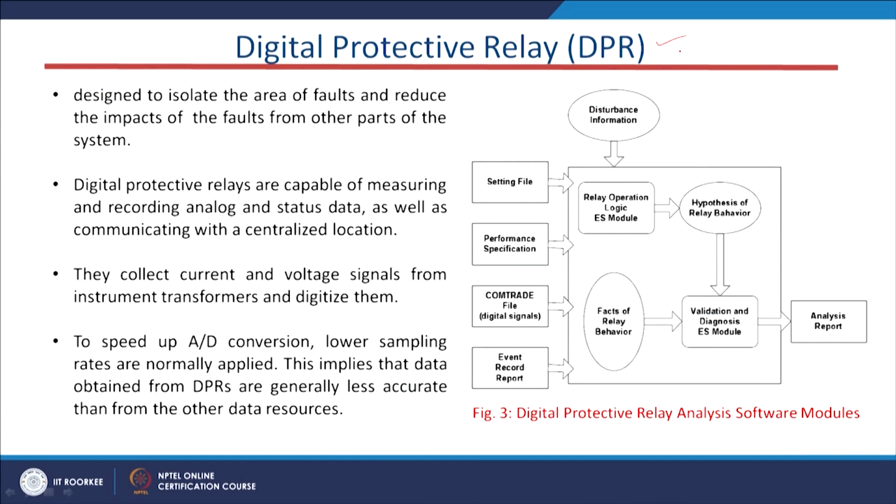Now, we have another device, that is the digital protective relay. We will discuss it more in our subsequent classes, when we talk about the protection part of the smart grid system. This digital protective relay also takes a very good decision, and tries to protect every piece of equipment, in fact the generators, transformers, transmission lines, feeders, loads. Every equipment is basically protected by one digital relay, which takes the voltage and current information, operates with certain signal processing techniques, and gives the trip signal to the circuit breaker.